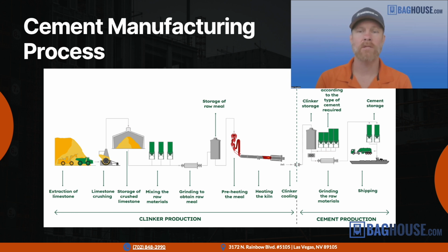Where is dust or where is product moving from point to point, from a conveyor into a silo, up an elevator, and understanding which of those transfer points require dust collection. It'll probably be most of them. And at that phase, what kind of dust is being produced? What's the components of the product and the dust at those points in your part of the process? What is the sizing and the quantity of material being moved, and how do we design a system to capture dust correctly at each point?